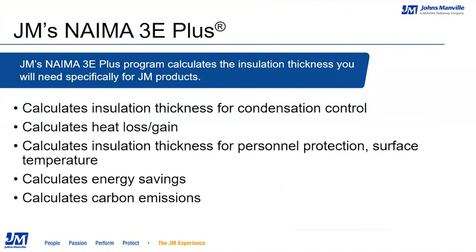Going back to the topic of design considerations, I want to discuss a tool that helps with determining appropriate insulation thickness. That is the NAIMA 3E Plus program, and it has a lot of interesting features. Not only does it provide insulation thickness recommendations for condensation control, but it can also calculate heat loss and gain and provide calculations for thickness based on personnel protection. This would, for instance, make sure the surface of the insulation stays within a safe range. And also, this tool has some great features that could provide a building owner an idea of their energy savings or carbon emission reduction by using various insulation options.